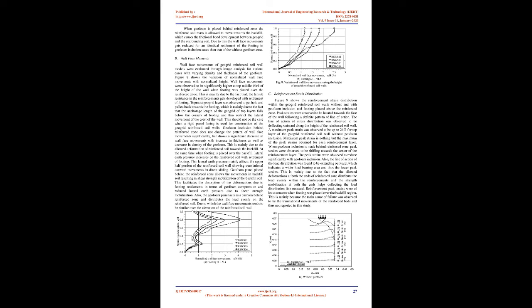L-shaped plastic markers were glued to the geogrid layers to monitor the movements during the tests with the help of image analysis. A thin geotextile was used at the wrapped face of each layer so as to avoid any sand leakage through geogrid openings. A digital camera was fixed on a PVC stand arrangement to facilitate undistorted monitoring of the geogrid reinforced soil wall models. 2 sets of lithium battery-operated LED lighting panels were used to maintain a constant intensity of illumination throughout the progress